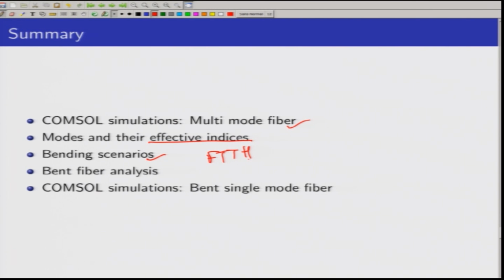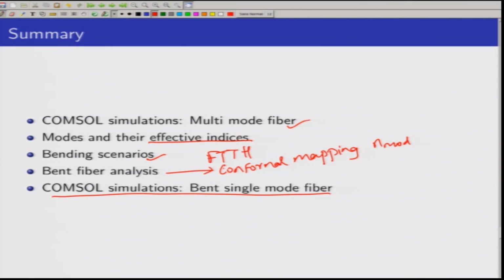Then we went on to how we are going to analyze the bent fiber, where we applied the conformal mapping technique and obtained a modified refractive index, N mod. We applied this N mod into COMSOL and performed a simulation for a bent fiber, and have seen how the mode really looks like when a fiber is bent, and compared it with the initial results of a straight fiber.